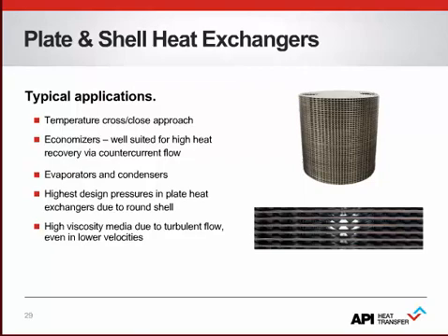Plate and shell type heat exchangers are typically used for applications with close temperature approach and higher pressures and higher temperatures, but also in applications where the fluid is either dangerous or of high value due to the low hold-up volume.